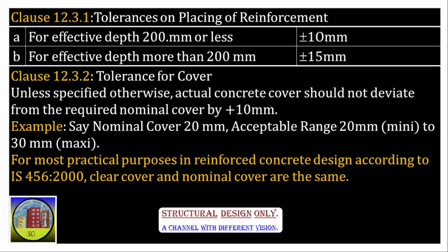We have to maintain nominal cover as close as possible. Stricter tolerances might be required in specific situations. In such cases we have to refer to design documents. For most practical purposes in reinforced concrete design according to IS-456-2000, clear cover and nominal cover are the same. Following these guidelines, we can maintain the proper cover for the elements.